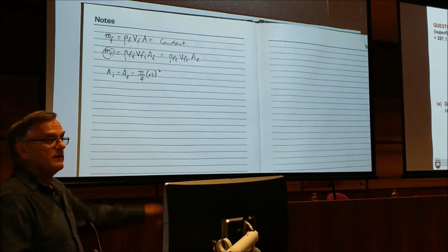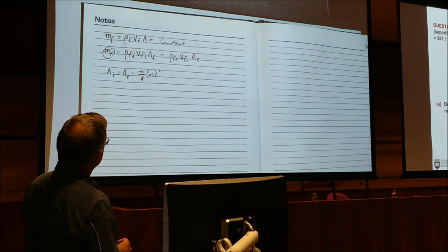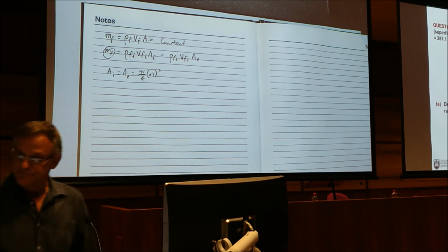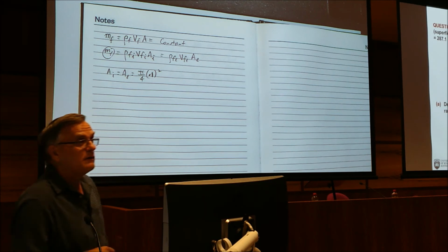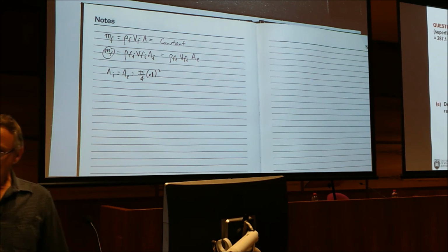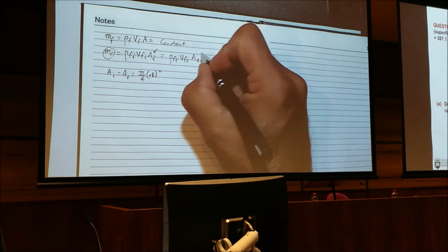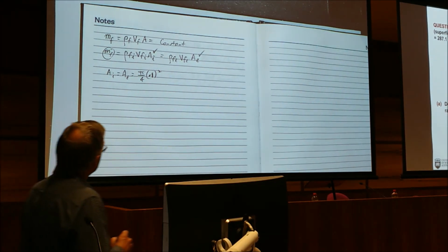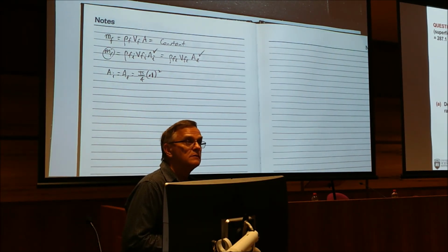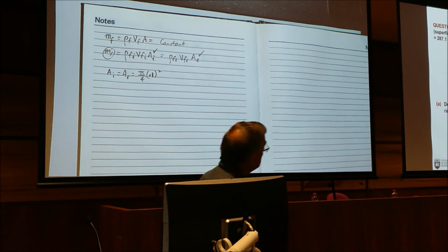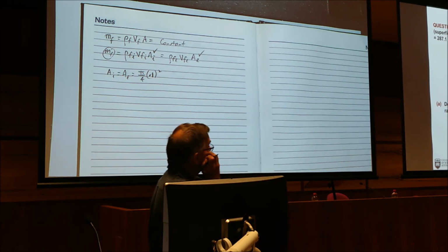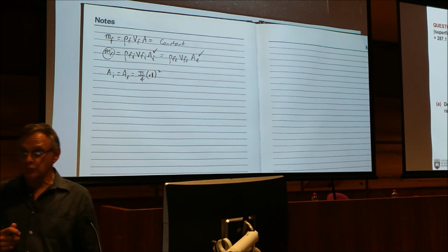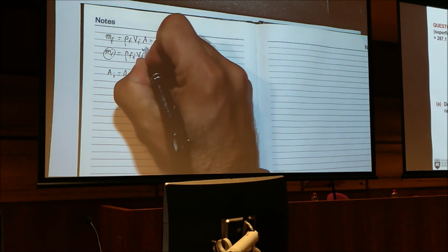I've got my calculator here, but that's easy to calculate. I'll let you work that out. Okay? The diameter is 0.1 metres. So the diameter is 100? Yeah, 0.1 metre. So use SI units. So we know AI, we know AE. Do we know VFI? Yes, we're given VFI, aren't we? The minimum pickup velocity at the feed point is 19.2. So we know VFI.